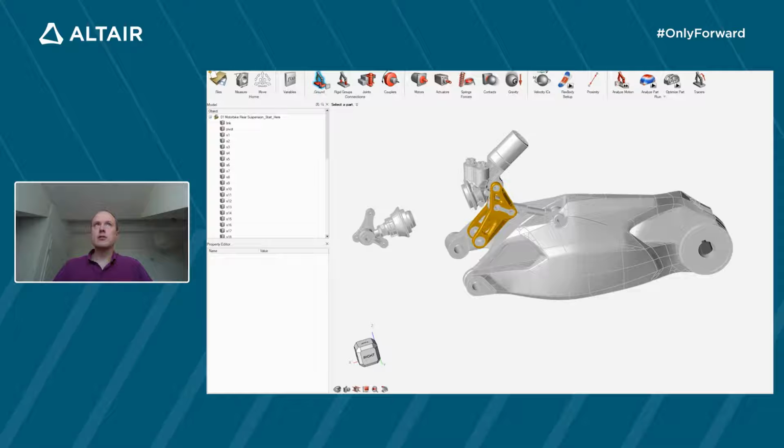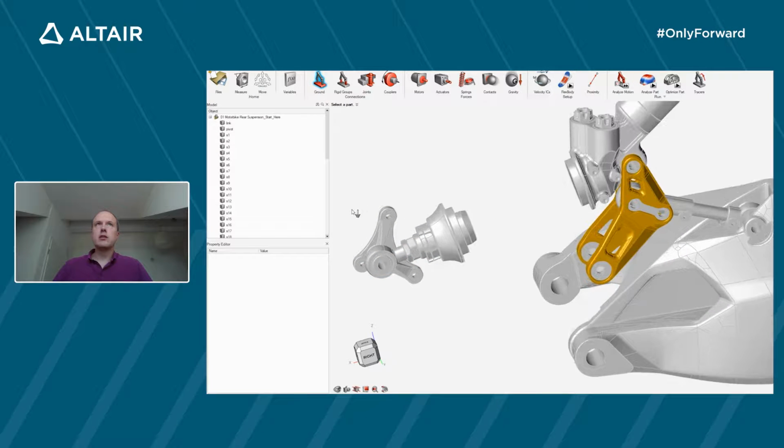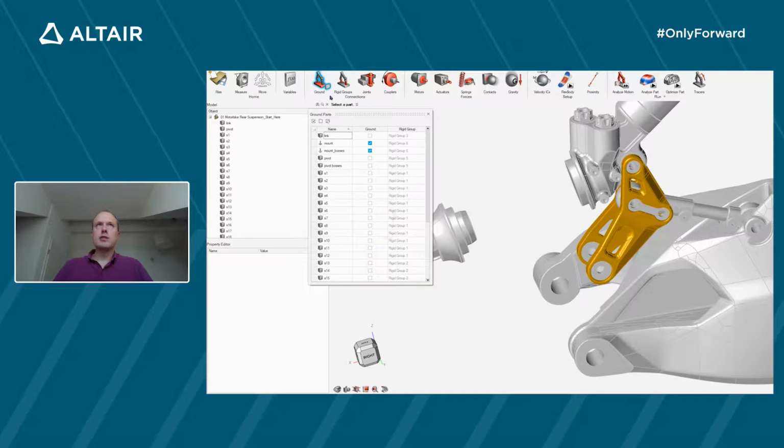To access the menus here, what you need to do in Inspire, it doesn't matter in which menu band you are here, it always is the same procedure. To activate a function, you will then see the mouse cursor activated, which will allow you to select one or multiple parts. And in that case, I defined those two parts to be the ground parts of my simulation, basically meaning that they are fixed to the motorcycle and are not allowed to move during the simulation. Now, every menu, or almost every menu, has again a table next to it, so you can review what you defined, and you will see that those two parts have been defined as the ground parts.